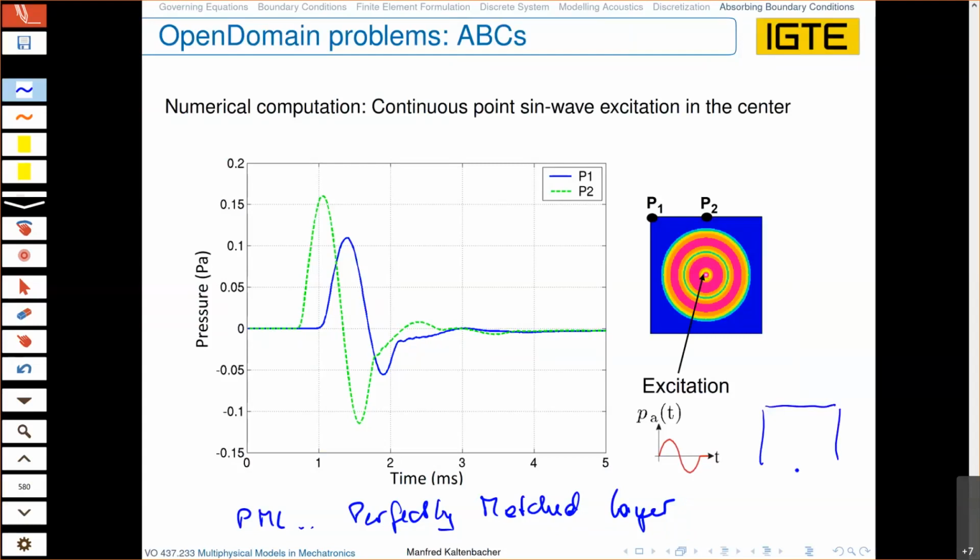You have your propagation domain, and you add an additional domain, the damping domain, which needs in thickness direction only about 2 to 3 elements. This is our so-called damping domain, where we try to damp out all the waves which are entering it. And the big challenge is that at the interface between propagation domain and damping domain, we have this so-called perfect matching. This is the optimal way how you can do it, but it is heavily involved concerning theory, and also, once you have a good formulation, concerning the implementation.